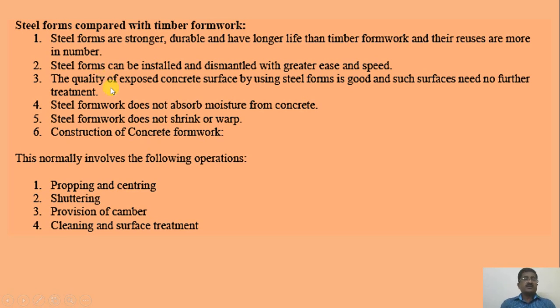Steel forms can be installed and dismantled with greater ease and speed. The quality of exposed concrete surface using steel forms is good, and such surface needs no further treatment. Steel formwork does not absorb moisture from concrete. Steel formwork does not shrink or warp.